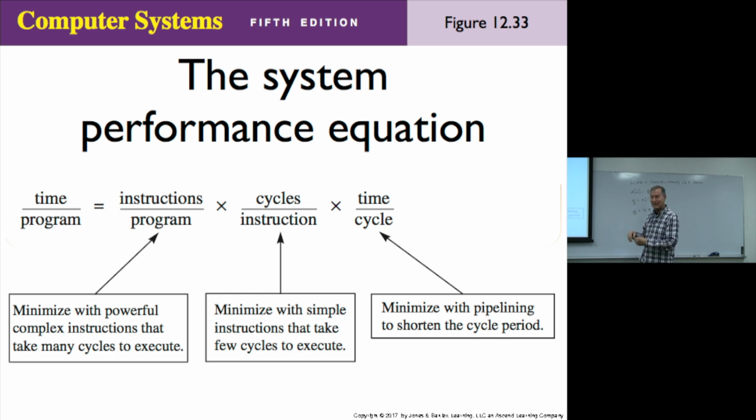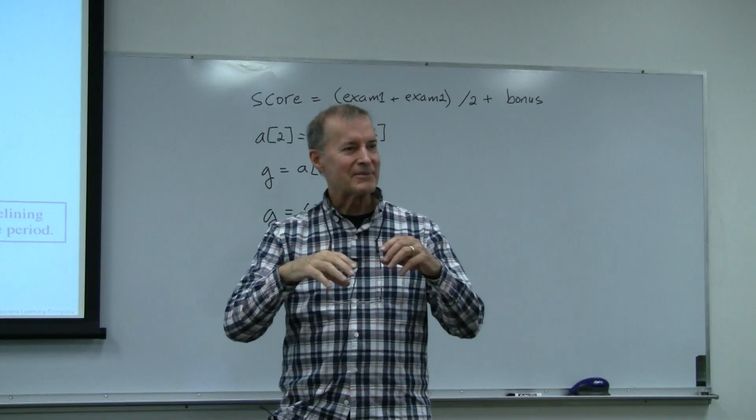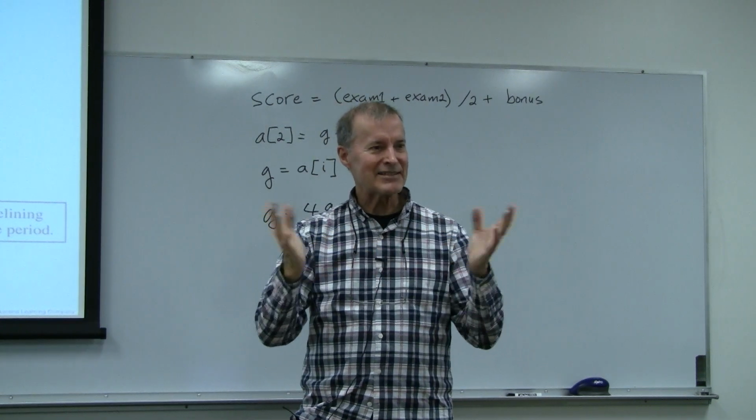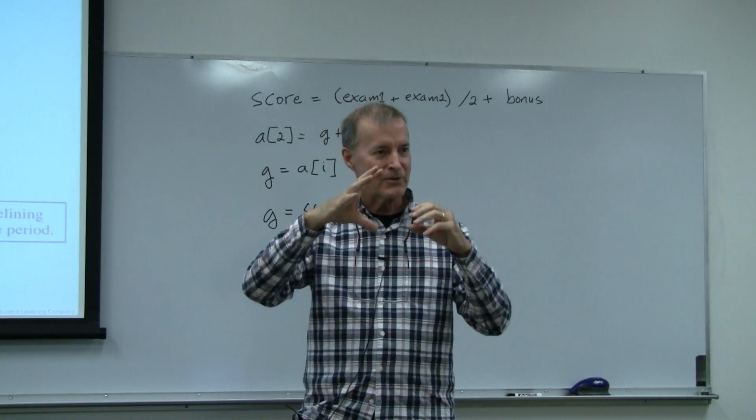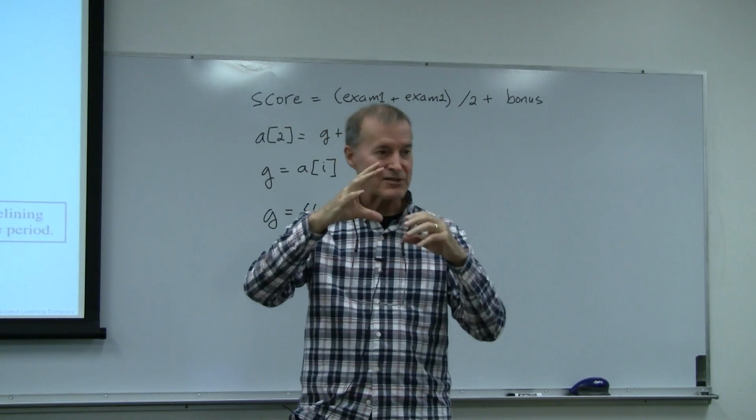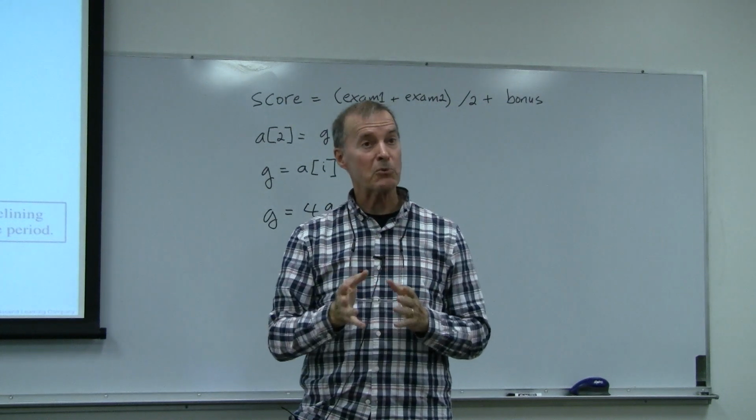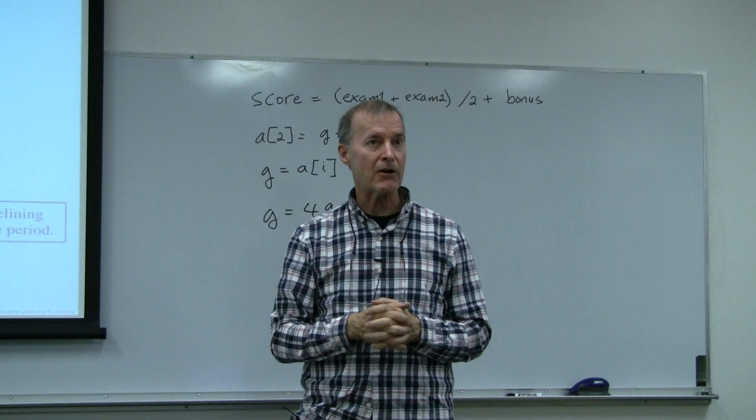Are you with me? Conversely, with a RISC machine, you minimize the number of cycles per instruction, all the way down to 1. But that means that you have more instructions per program. And we just saw that you have to do in 2 instructions what you could do with 1 in Pep9. So it's debatable which one is better, because there's a trade-off. You minimize this, you maximize this. And furthermore, it's also complicated by other questions like power efficiency.